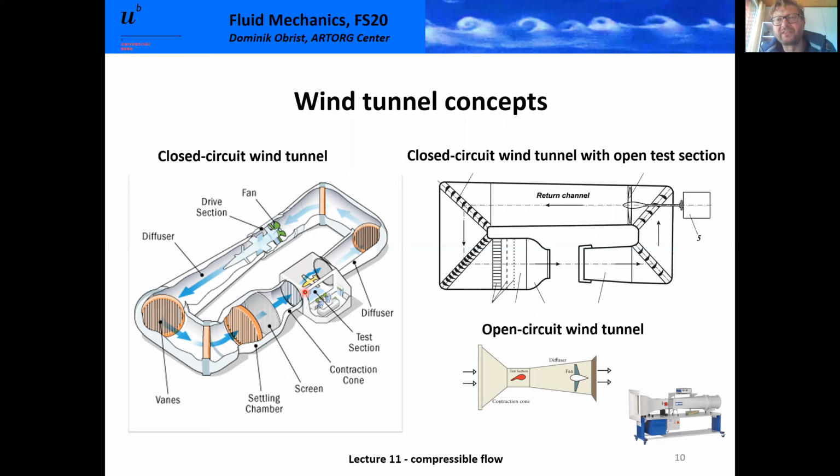People are also talking of silent wind tunnels, and by silent, they're not really talking about the noise, because these wind tunnels actually make a lot of noise. They're actually talking about silent in the sense of having little turbulent disturbances. So usually you want to obtain a flow as laminar as possible as it comes in to your test section, such that you have a well-defined laminar inflow, and you can study, for instance, transition phenomena, transition to turbulence phenomena.